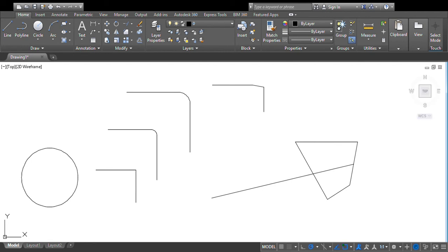So this is the chamfer command. Select chamfer. Then you can do one thing, you can just give distance. Instead of angle you can give distance, type D and enter. So it is asking for the first chamfer distance. First chamfer distance we will give 10 mm, enter. Then it is asking for the second chamfer distance, you can give 10 mm. Then you select the first line for chamfering and the second line for chamfering, so that you can get the chamfer also. Then you enter that.